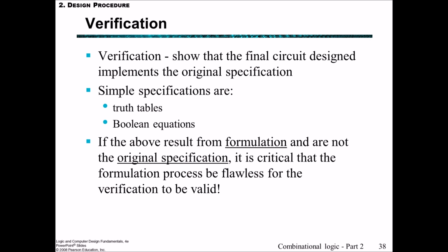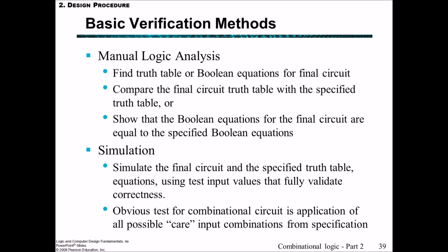We want to compare the final circuit truth table with the specified truth table. There's 2 main ways of verifying, one being the manual logic analysis, which is fine if the circuit is quite simple. We would find the truth table or the Boolean equations for the final circuit that we've created, and then compare the final circuit truth table with the specified truth table. Using a computer, we could simulate the final circuit and the specified truth table using different test inputs and make sure that they match what we expect.